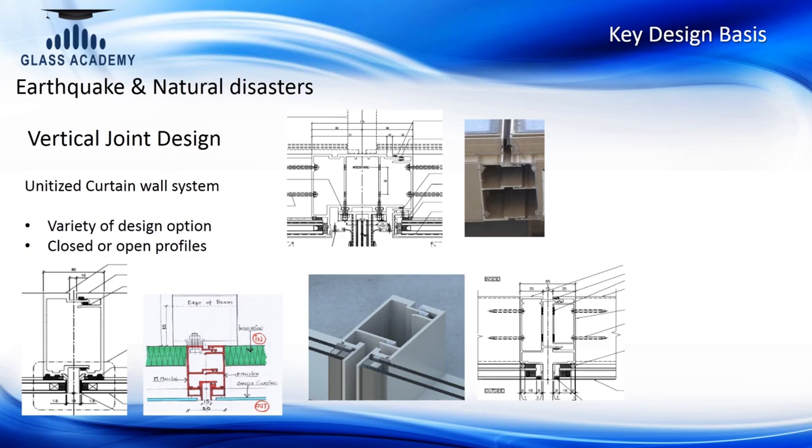And the primary concept here is there is aluminum framing which is supporting the glass, and the glass is supported with a structural sealant, or sometimes it may have a mechanical fixing. And the shape of this aluminum profile could be very different from project to project, and each panel shape is defined by many different factors.